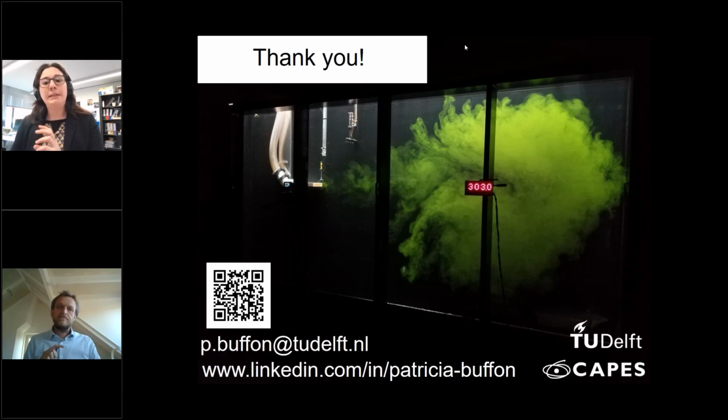Not entirely, but yes, part of it was transported downstream. That's something that I will look at in more detail now with the images. But we did have, for instance, bed form formation. There is deposition over time. Overall, there is deposition, but in the first minute or two, the turbidity current seems to be more efficient, which makes sense because the scouring is not so deep. But there is a significant quantity of sediment being transported downstream.